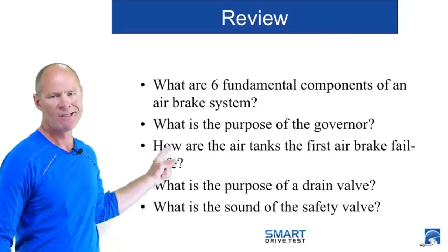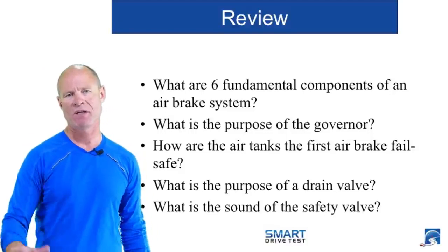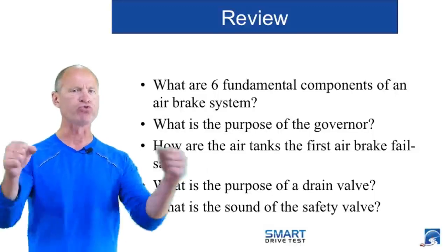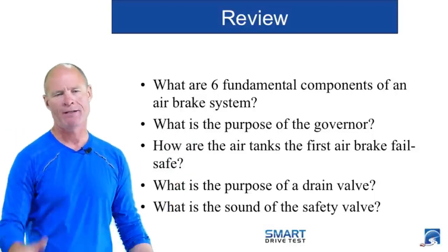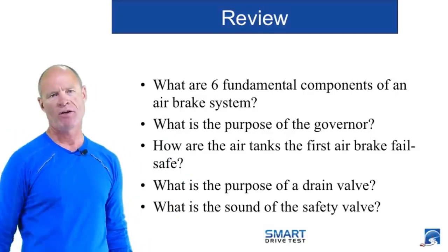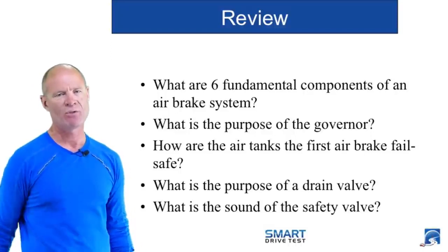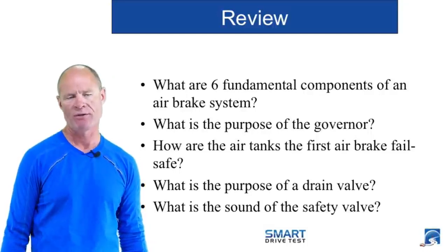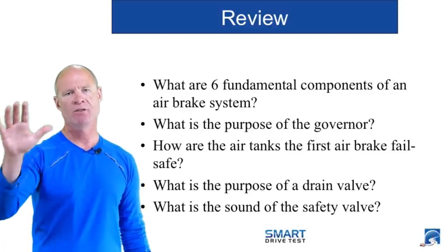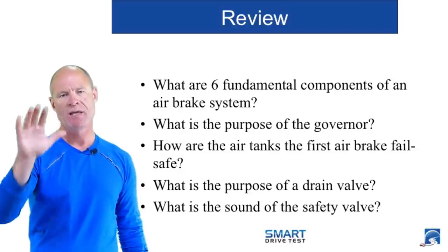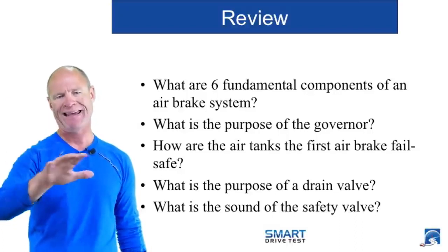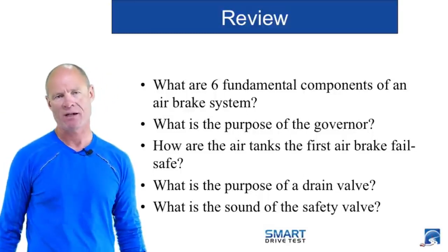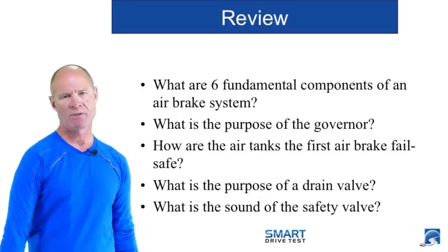And the last question: what is the sound of the safety valve when it blows off at 150 pounds per square inch? The sound is a machine gun. That is the sound of the safety valve blowing off excess air in the system, because if you have too much air, you could cause damage to the system and potentially to yourself or other people around the vehicle. So all tanks used in industry and for commercial uses have a safety valve that blows off excess air or vacuum. The purpose of the safety valve is to prevent the tank from either exploding or imploding.